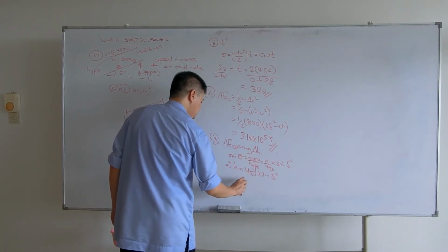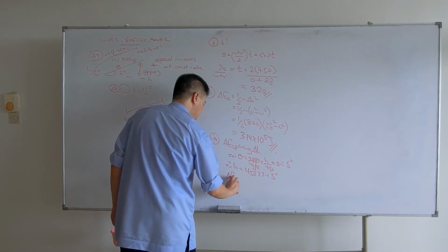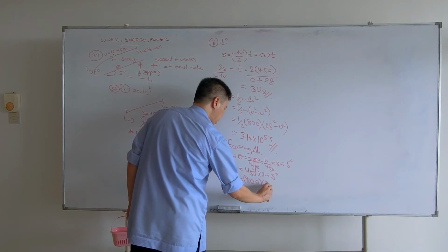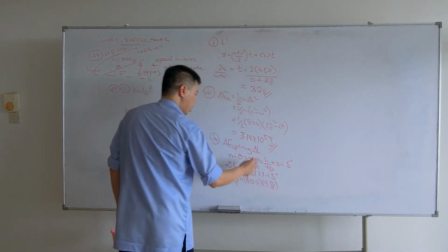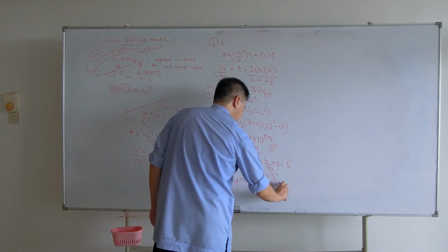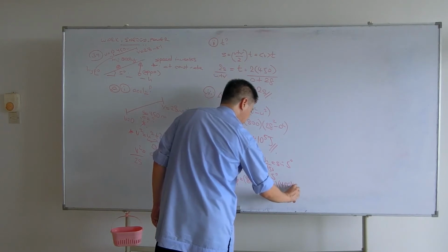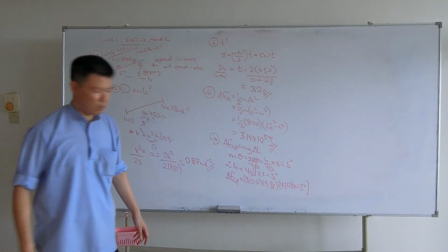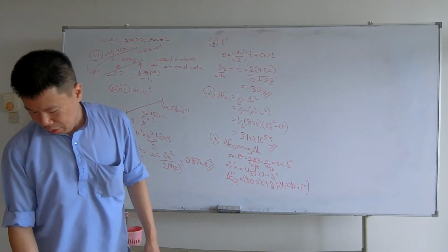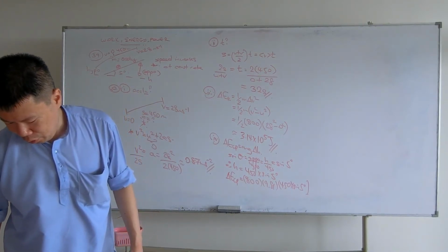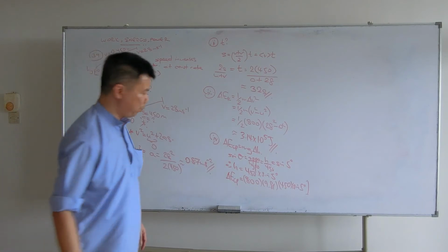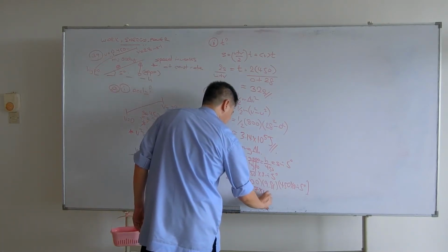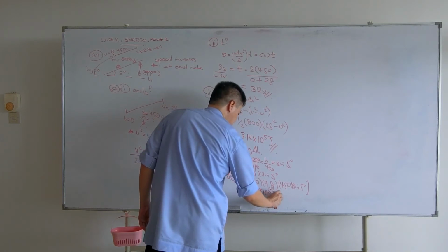Using this equation, delta EGP is equal to 800, your mass, times g, 9.81, times the delta h, which is 450 times sine 5 degrees. Please use a calculator. Hopefully by the time you pause this video, you should get around 3.07 times 10 to the 5 joules.